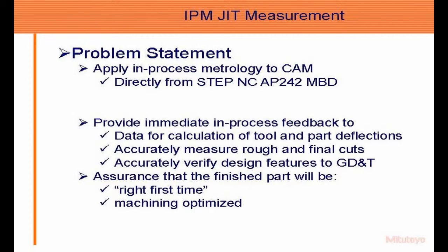It'll accurately measure rough and final cuts, accurately verify design features to GD&T, and this gives us an assurance that the finished part will be right the first time with machining optimized, because it will get that feedback loop of the data from the inspection at any point in the process.